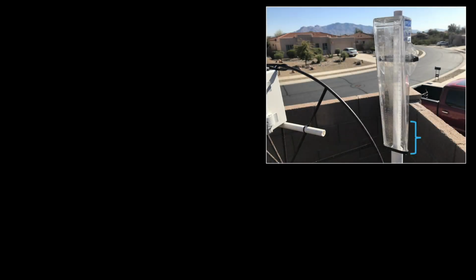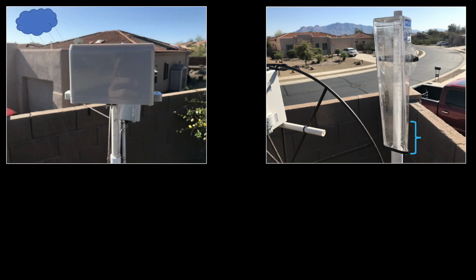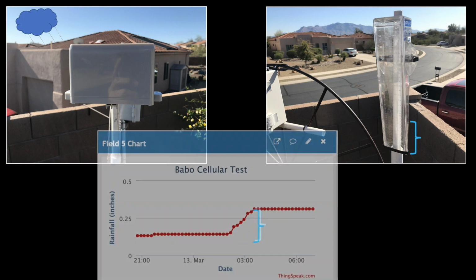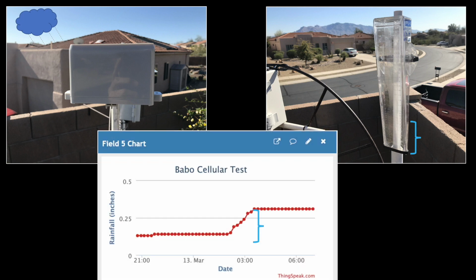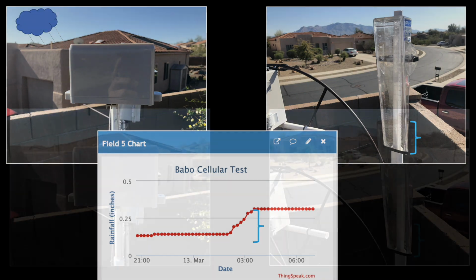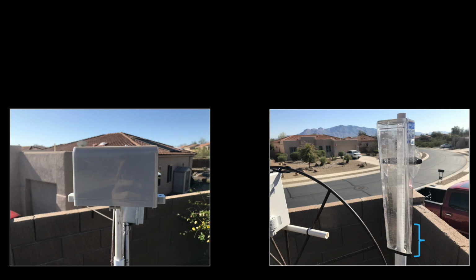Next, I'll review a method developed for determining rainfall depths using an analog gauge, and then use that method to test the accuracy of my tipping bucket gauge via reference to data posted to the Internet of Things. This will help me capture the total error associated with my tipping bucket gauge, should accuracy and telemetry be a factor. Initially, it occurred to me that I could just pour the volume of water for a given rainfall depth from the analog gauge into the tipping bucket gauge and then compare the results.